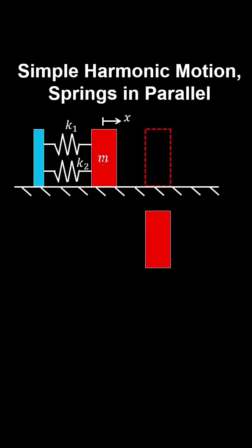Suppose we have a block attached to two springs in parallel, and we give it some initial condition, and the block oscillates at some amplitude a. Therefore the forces in the springs are restoring forces, and are generally not the same magnitude because the springs have different stiffnesses. But because we treat the mass as a particle that only translates on this frictionless surface, we would visualize these forces passing through the center of mass and not producing any torques. So the springs would deform by the same amount that the block displaces from equilibrium. And that gives us the following equation of motion.